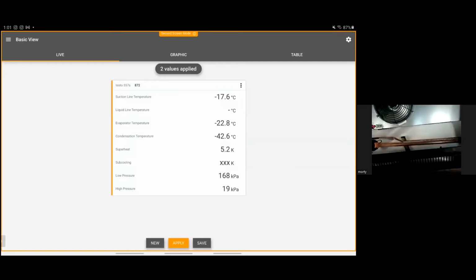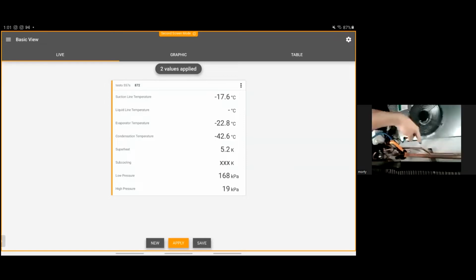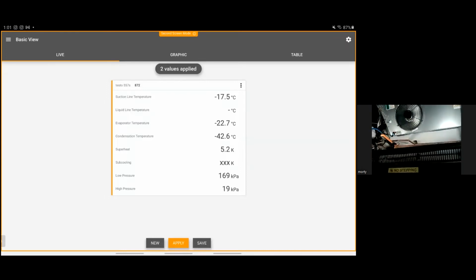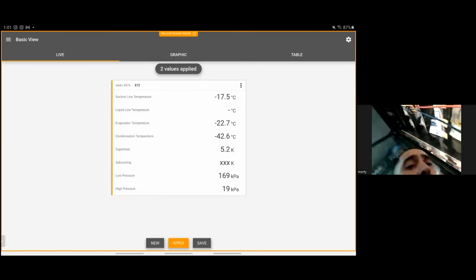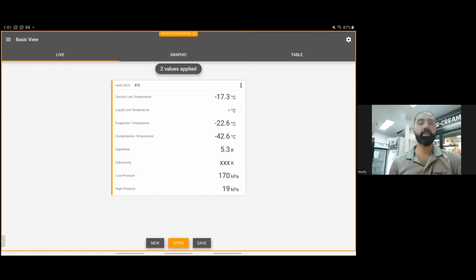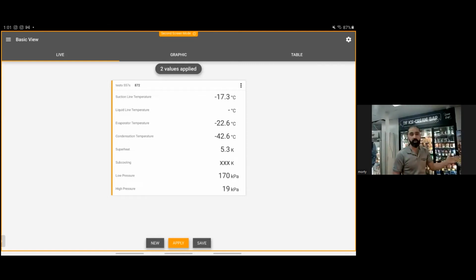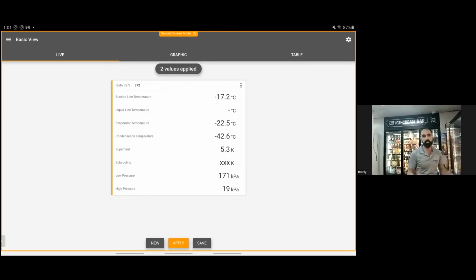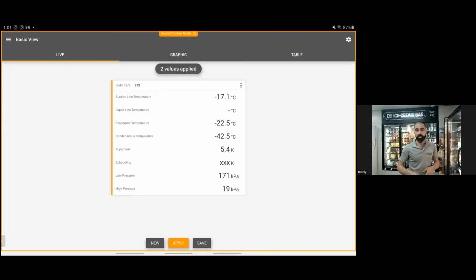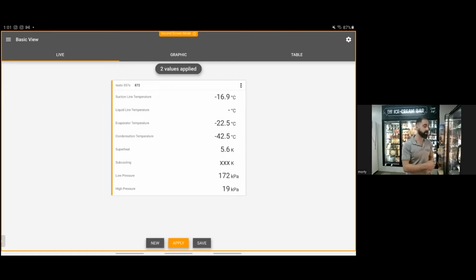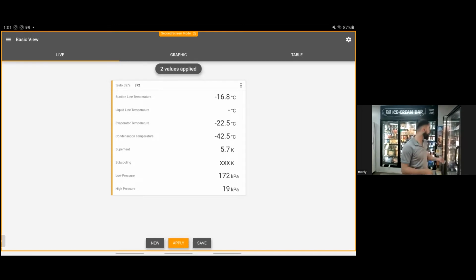So that's what I was talking about. You've got the liquid line right there, you've got your suction, and it's soldered all the way through. That's a good 3.5 meters of heat exchange, and it makes a huge difference. If my temperature leaving the evaporator is minus 17, minus 18, by the time it gets out the other side, it's actually 0 degrees or even sometimes 5. It really depends on the liquid temperature that it's feeding in. It's all controlled by the liquid temperature at this stage.